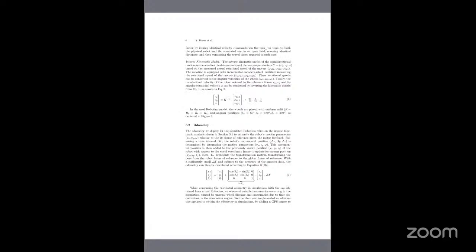Then coming to the odometry. This is the main part of ROS navigation. Okay, suppose the Robotino is moving, right? Now where is this Robotino? How much distance did this robot cover, right? How much rotation did it take? We can find all those data using the encoder. So the encoder will identify all those details, right? Wheel speed, inverse kinematics, and robot velocity.